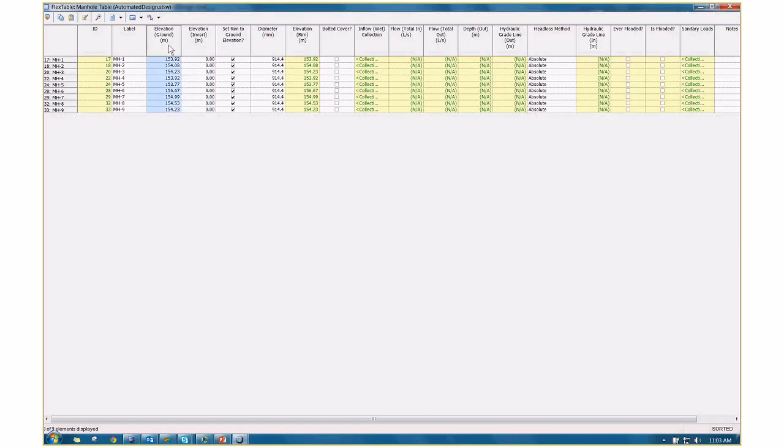So now using T-Rex, which you are already aware of, T-Rex is the terrain extraction tool, which extracts terrain from the contours. You are aware of that, right? Because I use the spot levels basically. Great. So you can either use spot levels or contours, whatever data you have, and you can assign the ground elevations to your elements.